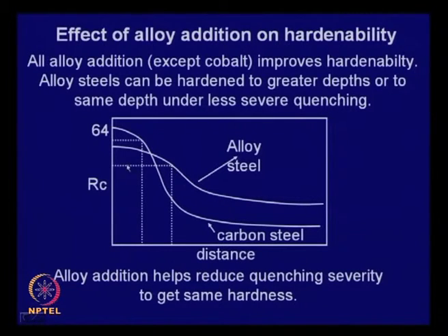So, one of the main advantages of alloy addition is that it helps reduce the quench severity required to get the same hardness at a particular depth.